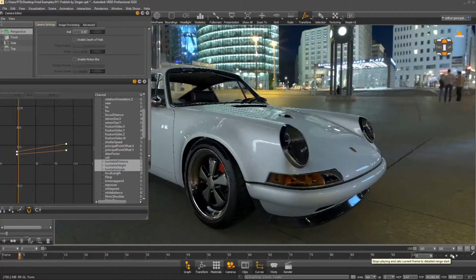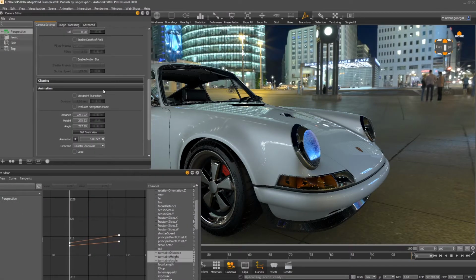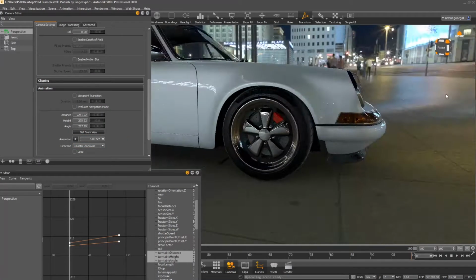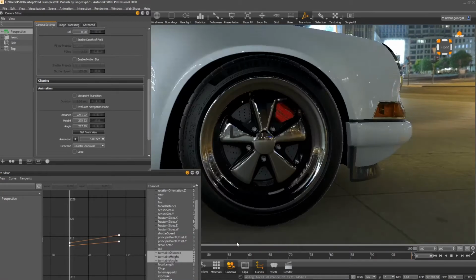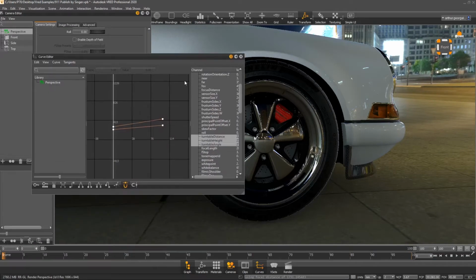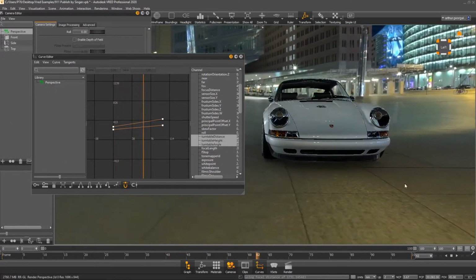So yeah, that's one way that we can use this turntable feature, which is under, if we open our camera, we come down to animation and get from view. So again, it's really important to make sure we control and right click to set our view. Now, because I've done that, okay, it is just going to reset to where it was in that start position.